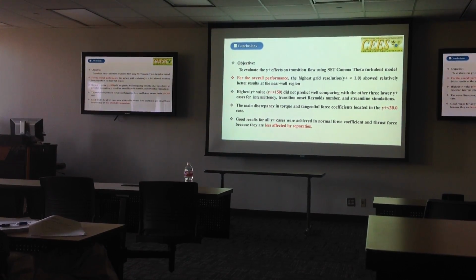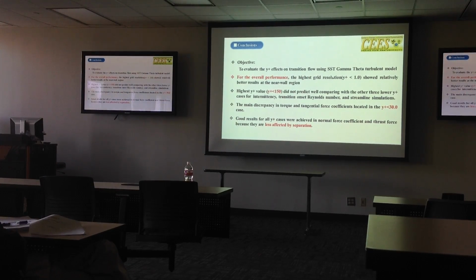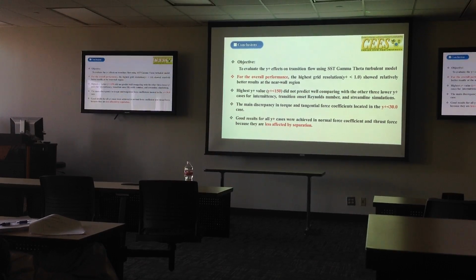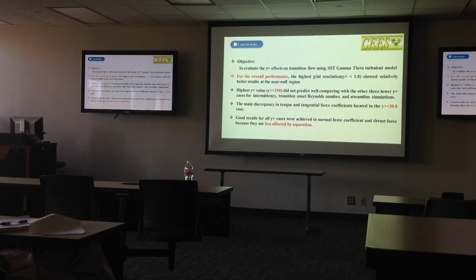We found that for the overall performance, the highest grid resolution, that means Y plus less than 1, showed good results in all the cases. Y plus less than 150 does not predict well compared to the other three in the intermittency, transition onset Reynolds number, and the streamline. These 3 parameters.